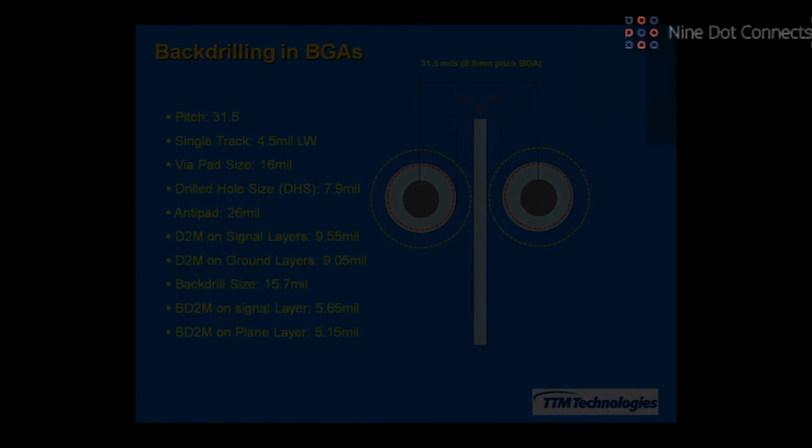Good clean stack up, have it all clear right up front. That's a big plus. That specifies both single-ended and differential, and the same line widths are not applied for both. That's very important.